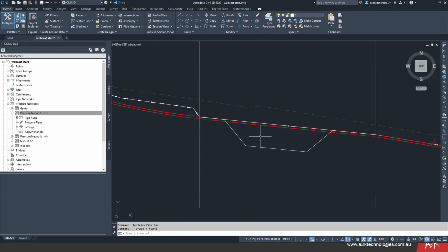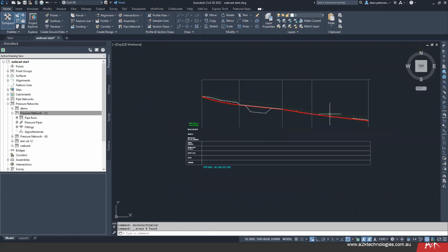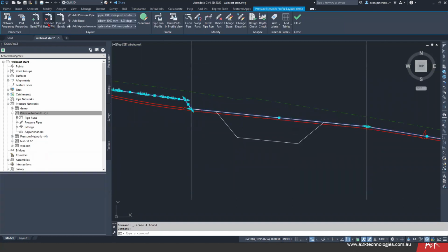for instance, that's in here, I've changed the scale. Oh, I haven't done my bends in here. I've changed the scale to this to 1:1. So I could just put in those 45-degree angles, and I can simply go and pick a pipe, and up in the ribbon here, we go add bend PVI on the left. And so I'll put in one, yeah, one, yep. And it's finding the closest bend to make that angle. And hopefully, this should be my 45s.